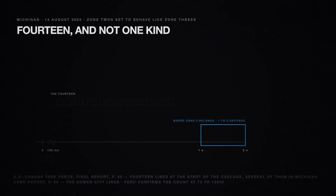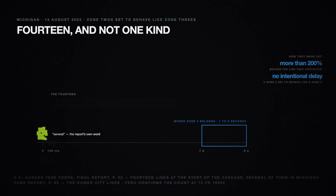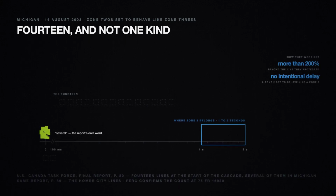Several of the elements that opened lines in Michigan that afternoon were Zone 2s, set to reach more than 200% beyond the line they protected, with no intentional time delay at all. That is the investigation's own description. A Zone 2 set to behave like a Zone 3, reaching past the far end of its line by a factor of 2, acting immediately.